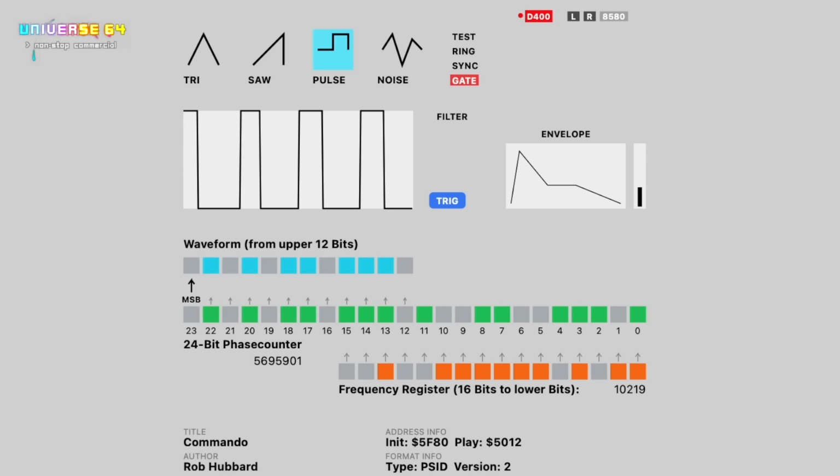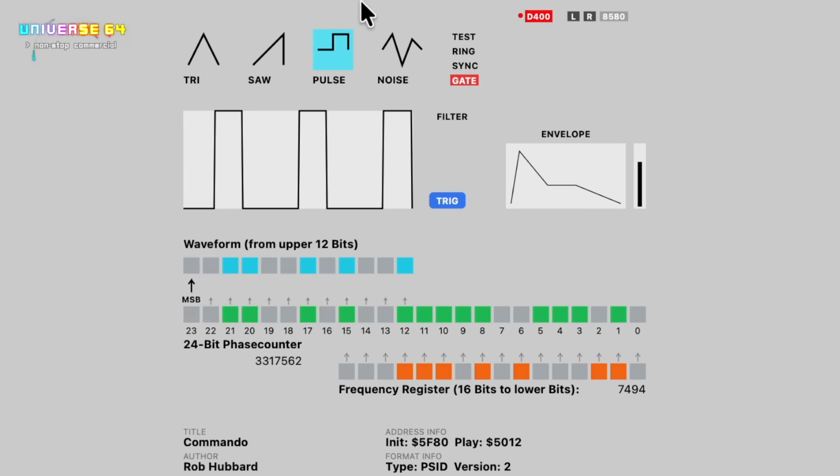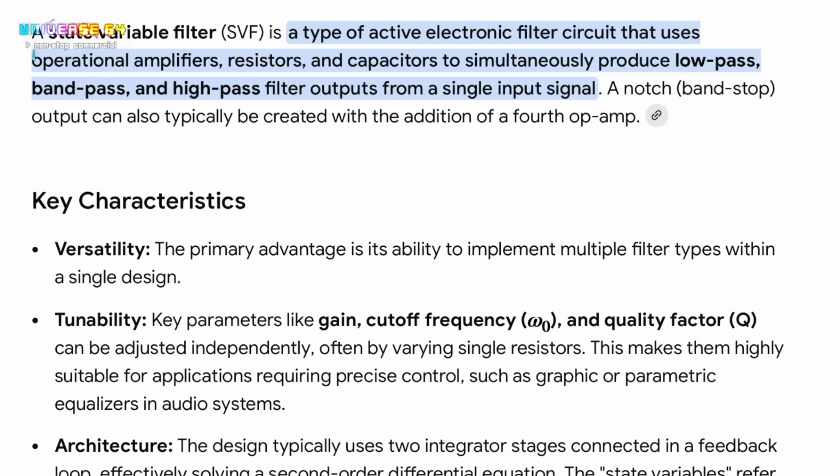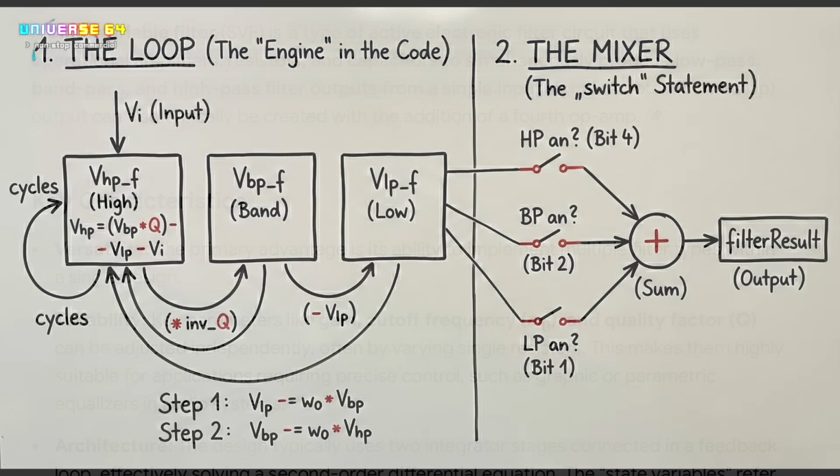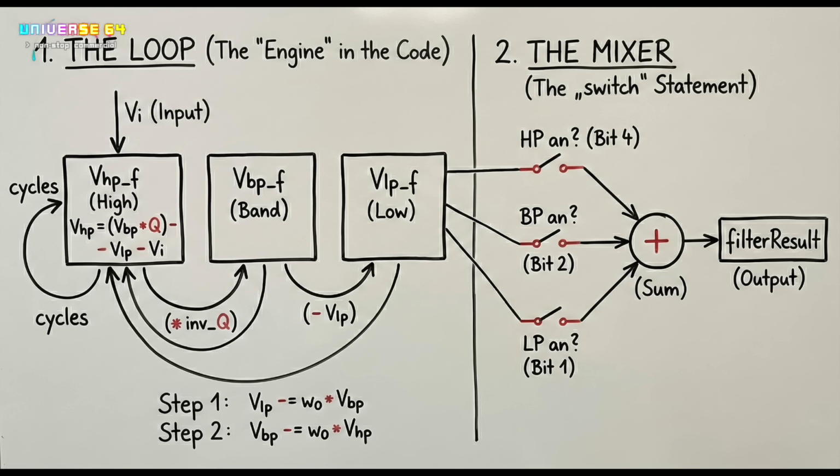Let's come to the last element of the sound chip, the filter. The filter is a state variable filter and also not witchcraft. There are very good explanations and formulas on the internet regarding how this filter works and is used. To save computing time, most replicas use fixed point calculations for the filter, which ultimately sounds a bit less precise. In the public domain SID, however, floating point calculations are mainly performed.